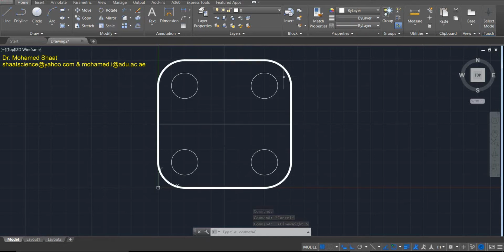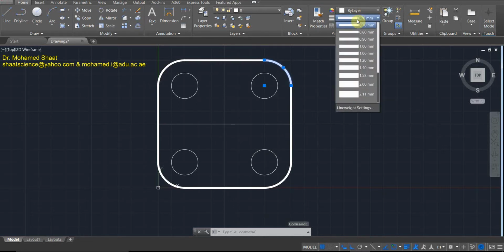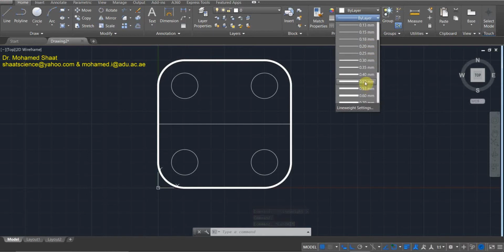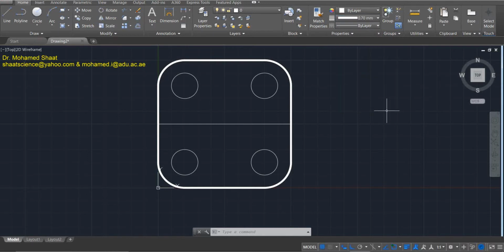And simply again, how it works, your objective is just to select the object, then you go directly to change the line thickness. How about if for some reason you forgot to select the object and you did change the thickness? Let's say, for example, I changed the thickness here to 0.7, but I didn't select an object, right?